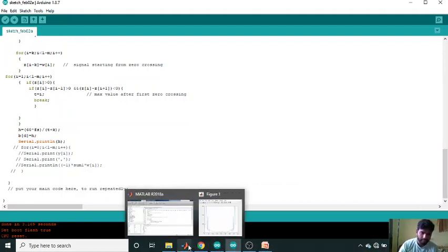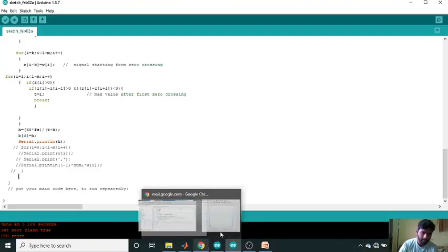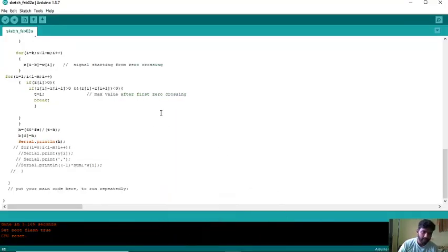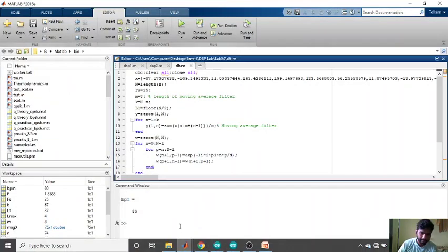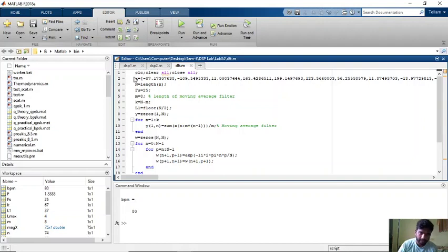And then we'll use the same method to find the BPM using MATLAB. We are going to do the same procedure. We assign the samples to a variable and find the length, that is, n is 75 and fs is 25 hertz, where the moving average filter length m is 8, and k is n minus m, to find the moving average filter output.